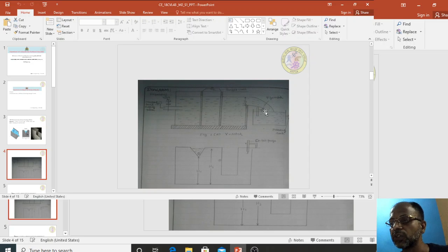So that flow of water is collected in this particular tank, called the measuring tank, because here we are measuring the collected water quantity. Therefore it has derived its name, measuring tank. And here there is a regulating valve. Some instruments will have circular regulating valves, some will have a straight regulating valve, through which flow takes place.